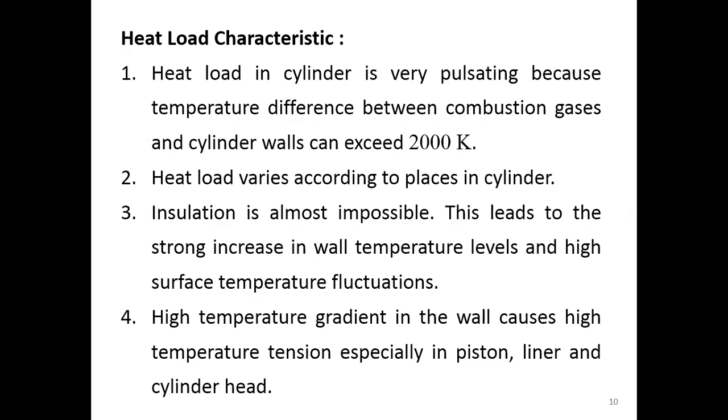So your insulation has to be flexible enough, and the thickness has to vary. If you don't use it properly, it may lead to a strong increase in the wall temperature level, and also high surface temperature fluctuations. The high surface temperature fluctuations happen because we are not operating the engine at only one speed or in one condition.